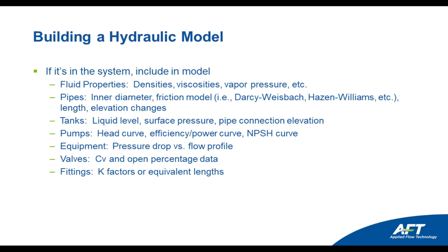That would be an example of where something is not modeled right, which just wasn't known up front when you were building a model. Another reason why model results may not match measured data is potentially the measurement devices might be bad, and you might need to replace those. Or there very well could be corrosion or fouling or various types of degradation in the system that's not accounted for. So all those are reasons why your model results may not match measured data.